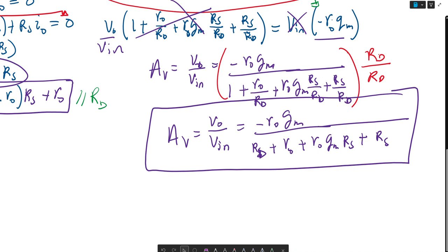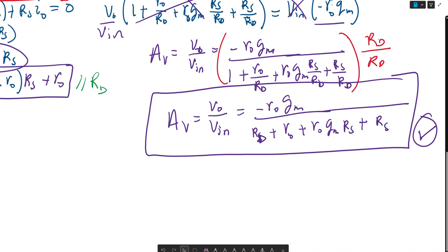But when you're doing small signal analysis, it's good to do this once and understand how to get this. But then when you're trying to estimate more complex circuits, we consider a lot of simplifications. For example, a simplification we consider is when RO is much greater than